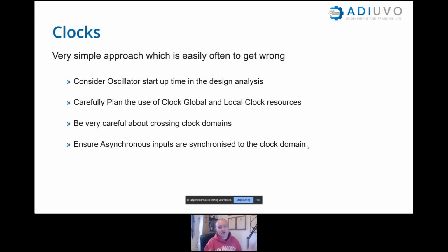We want to consider our clocks, and make sure about our clocks and our startup times. We want to consider start times on the clocks. We want to make sure that we carefully use any clocking resources, and we want to be exceptionally careful about clock domain crossing and about how we handle resets that are asynchronous as they go across clock domains. So we want to look at how we can resynchronize those to the correct clock domain.